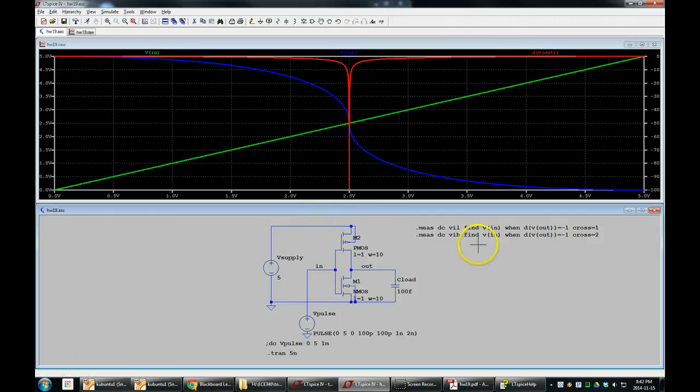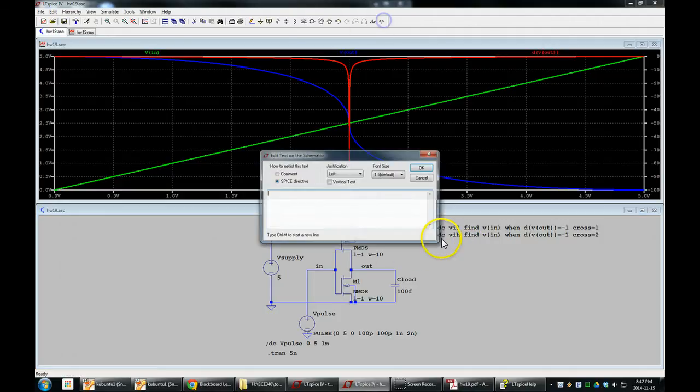All right. So what else did we forget to do? Well, we forgot the models of this transistor. Let's put those in. Otherwise, it used default parameters of all these. So NMOS, and it's an NMOS. We can do that. KP. The parameter is KP even for an NMOS. And that's 100 micro. VT0 was 0.6, and lambda was 0.01. Control M.